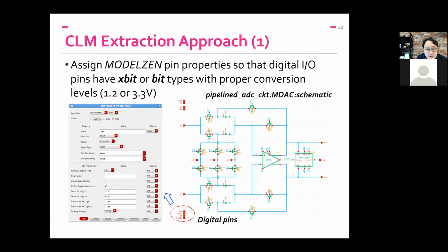For the digital signals, it's better to model them as the digital type, such as wire and reg in Verilog, or use our XBit type, which is just another digital type used by XModel. Because when we build the test bench, we would like to use SystemVerilog, which will supply the input using wire or reg signals. So it's possible for you to say, I want these to be bit, I want these to be XBit. We'll do that as a preparation step.